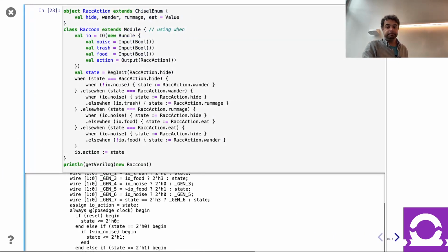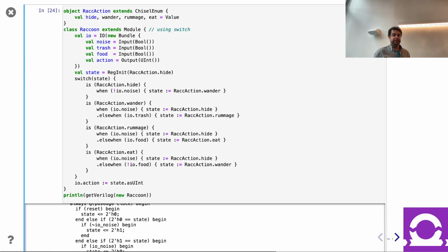But yeah, this is an example of a state machine. And it's very common. You're building a module and you have two or three states, right? And based on those states, you do something. Rather than always having such formal arcs and arrows, you might just have most of the code behave the same independent of the state you're in. And in a handful of places, depending on what state you're in, maybe you have a when statement or a mux to do the right thing. But like I said, it's still a good example for today to cover all these things working together.